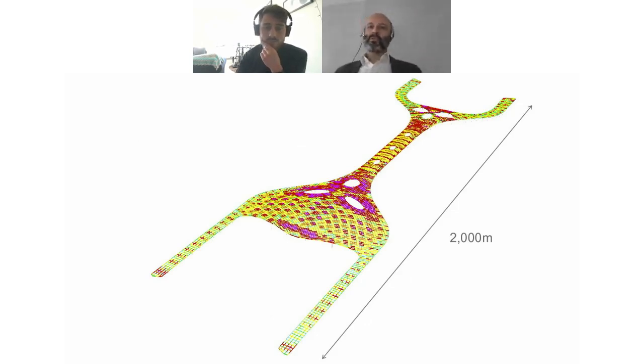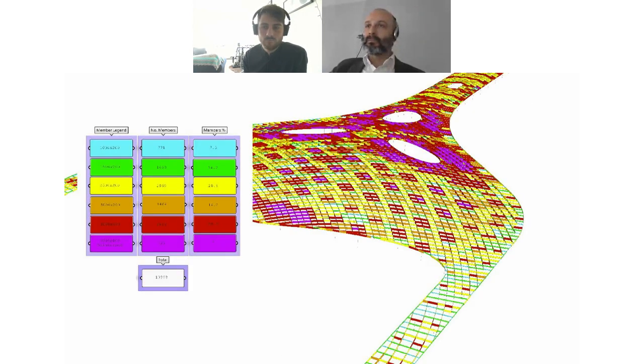Right, so this was quite a monster of a project that we worked on recently, a building that's almost 2 kilometers long with a roof area of something like 400,000 square meters. So designing a structure like this takes months, but this was a competition, so we didn't have that much time, and we needed to convince the client that if they wanted a sustainable airport, a timber roof structure should be their only real choice. But how do you design over 10,000 beams in an afternoon and calculate the volume of carbon you could sequester from the atmosphere compared to the steel alternative? The answer was developing a simple optimization routine, which, whilst it wouldn't provide you the true optimized design, got you pretty close, 95% there, but with a fraction of the time.